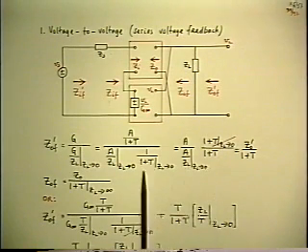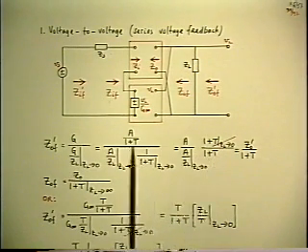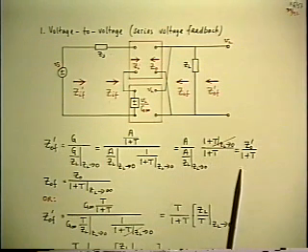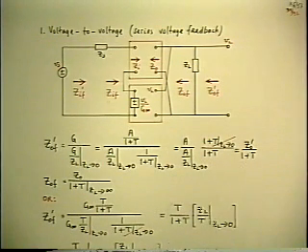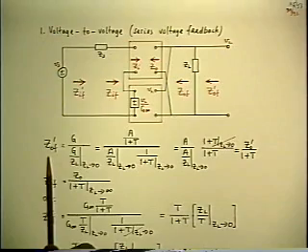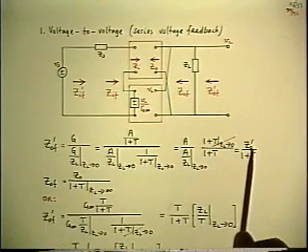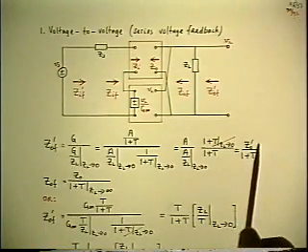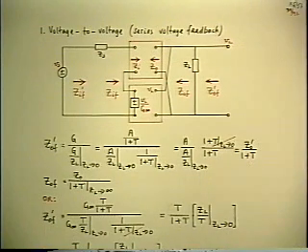Well, what else is left? Just the 1 plus T that came from the numerator. So that's the result, and it's a well-known result. You know it already. What it says is the outside output impedance of the amplifier with feedback is equal to the outside output impedance before feedback divided by the feedback factor. The same factor by which everything else gets changed.